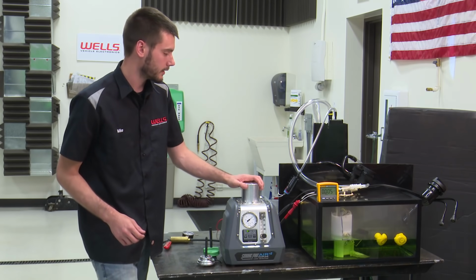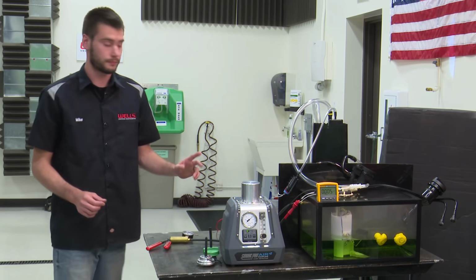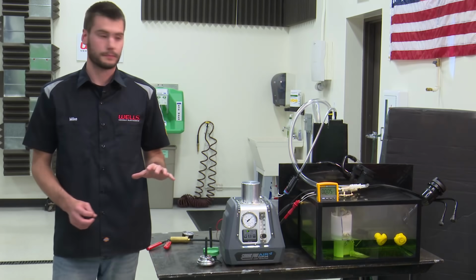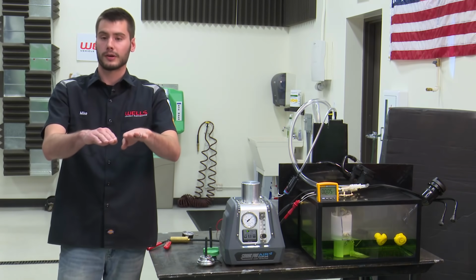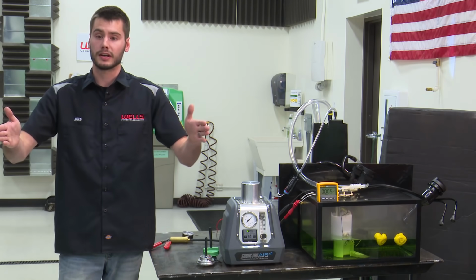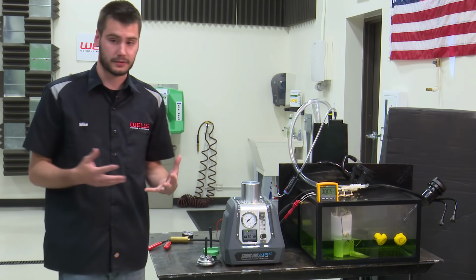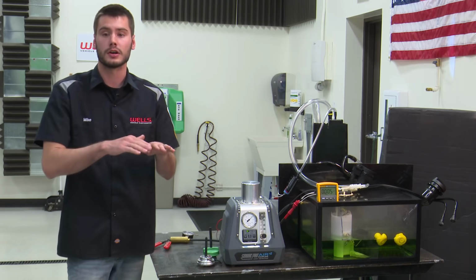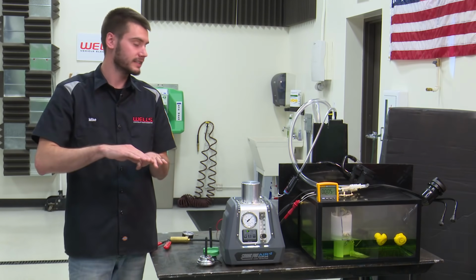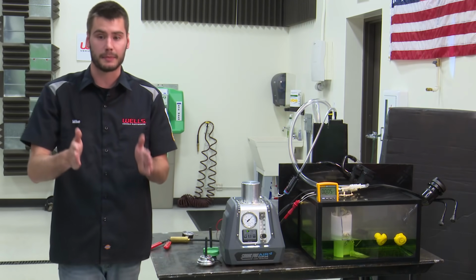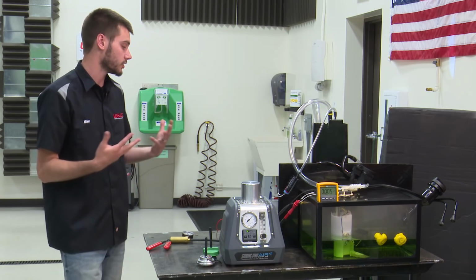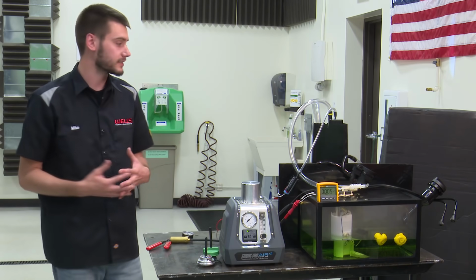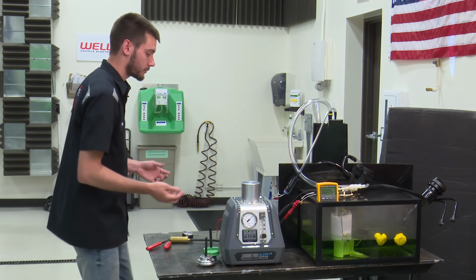But I'm going to go ahead and open up the vent solenoid. Oh, this is good to know. So the system passes the leak test, right? So we're below the threshold for the X amount of time, whatever it ends up being, we've passed, okay? The leak test is passed. But now what it does is it opens the vent solenoid and it watches for our vacuum or our pressure to get back to atmospheric in a certain amount of time. It has to do that quickly in order for it to pass the test for a vent solenoid blockage code or something related to the vent solenoid.